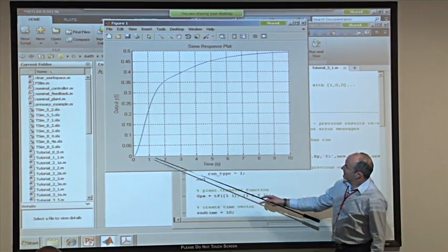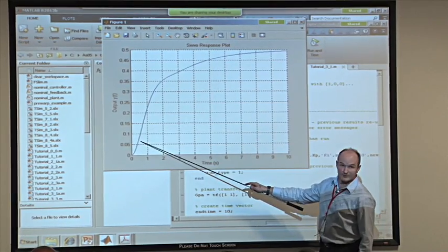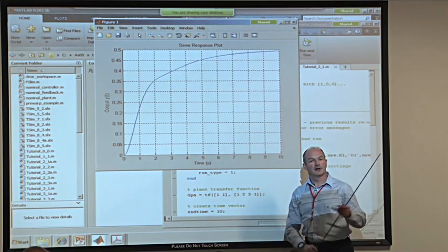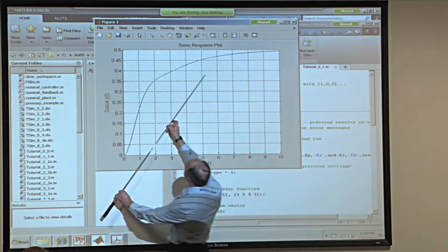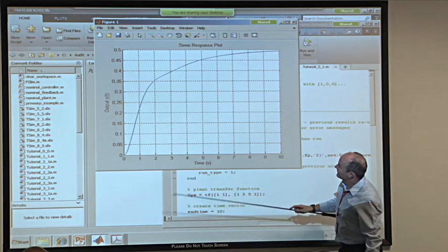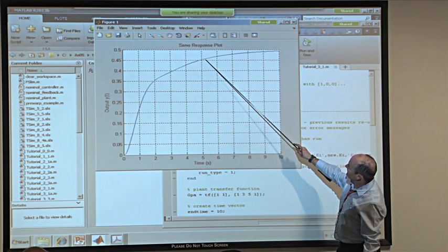It's also got a rise time of perhaps difficult to measure, but because of this left half plane 0, you've got this kind of kink thing. Remember, left half plane 0 gives you overshoot and faster rise time. So that's why this thing is starting to be pushed up here like that. That's the effect of the left half plane 0. So we might be looking at, I don't know, 10 to 90% about 5 seconds.